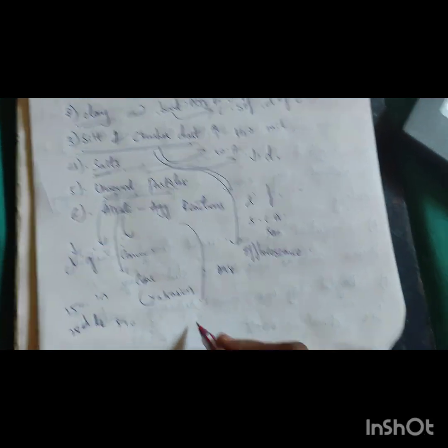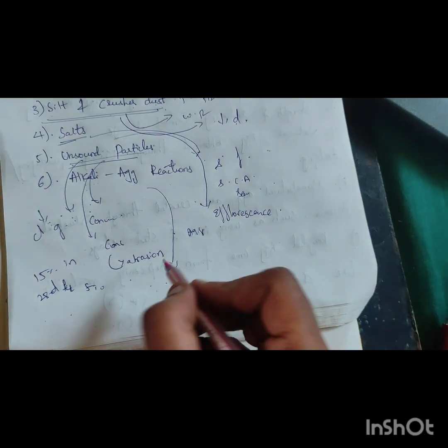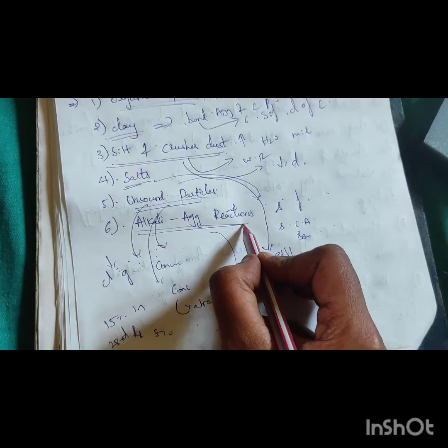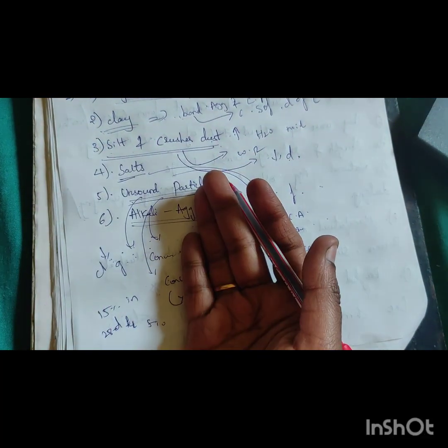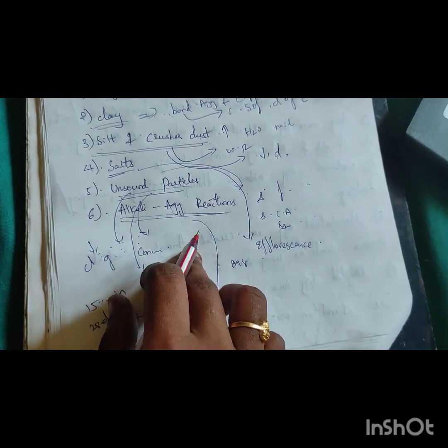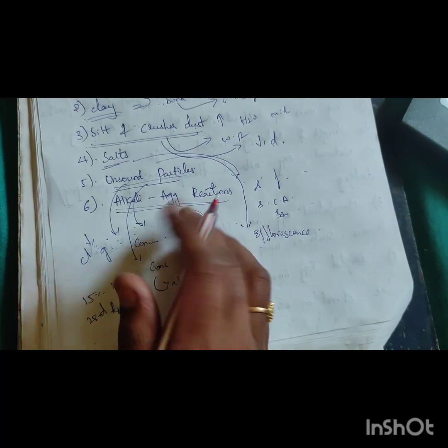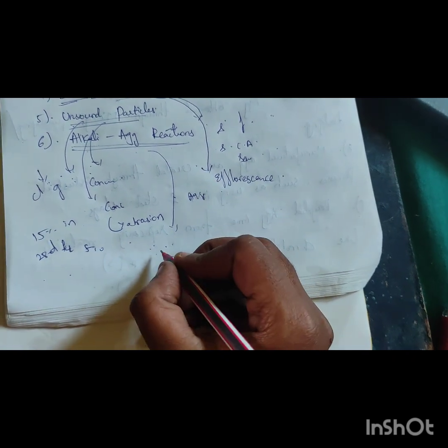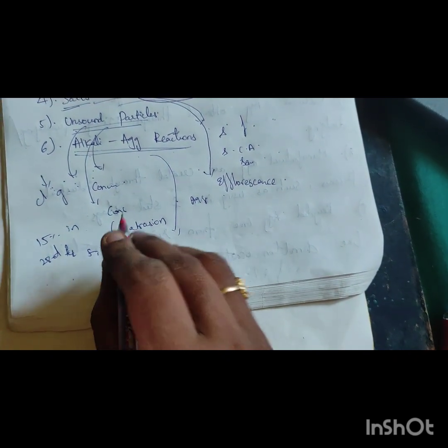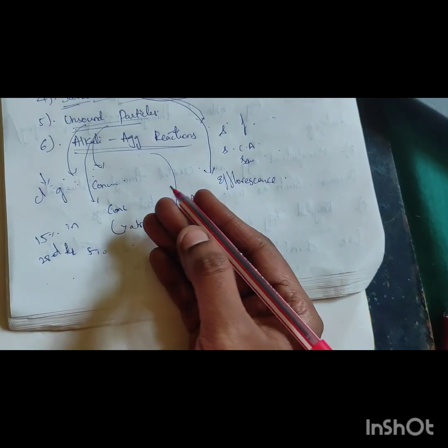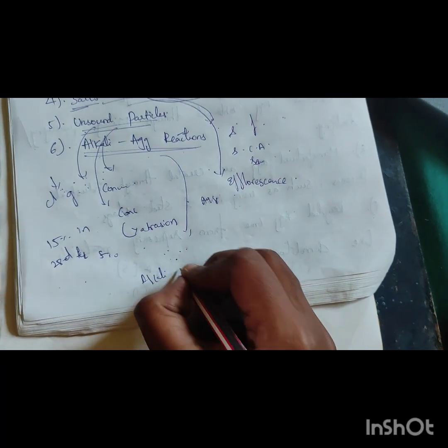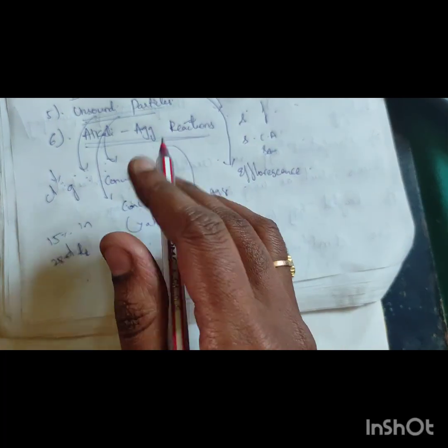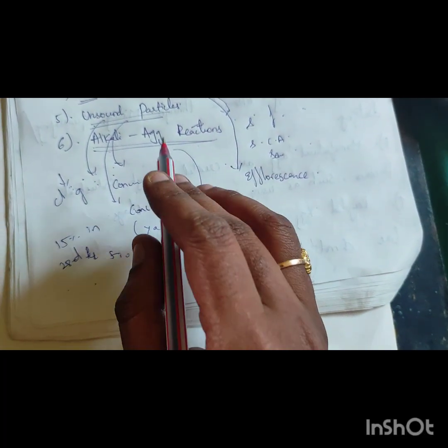The reaction between the alkali from cement and silica or carbonate from aggregate is called alkali aggregate reaction. The most common reaction is that between the active silica constituents of the aggregate and the alkalis in cement, which is called alkali silica reaction.